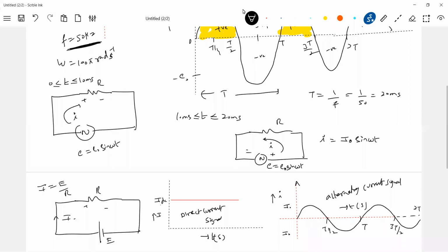So now what is the biggest problem? How do you measure this current? How to measure this direct current signal? What is available? I think an ammeter is available. So what I do is I just connect one ammeter here, no? And how to get an ammeter? From a galvanometer, I'll connect a shunt resistance in parallel. I'll just show it so it'll be easy for you. Then the same galvanometer scale will become an ammeter scale. I'm able to measure this current. So I do have an instrument.